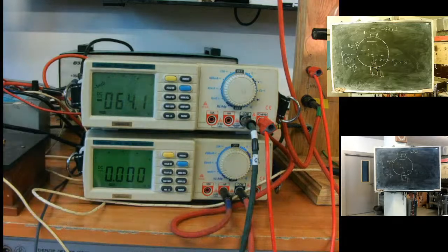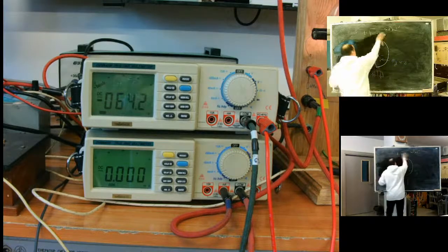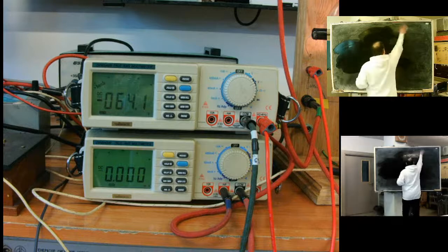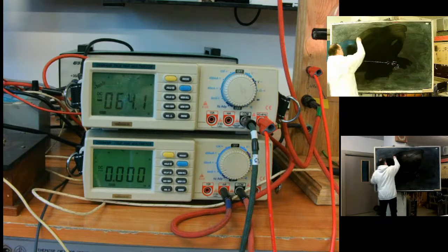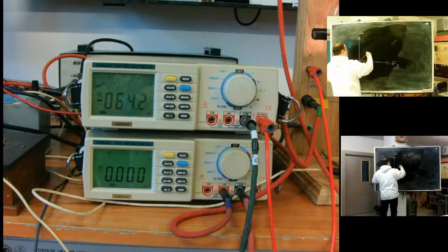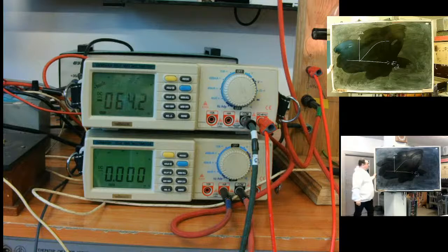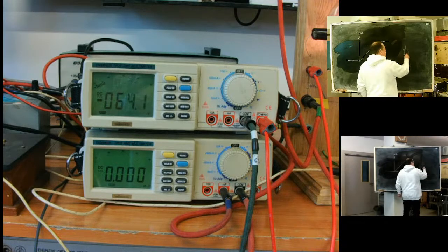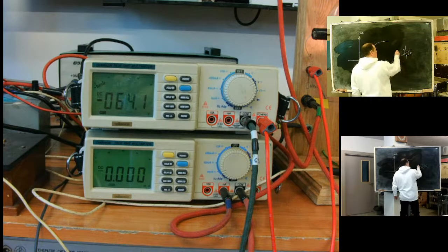I can draw a small curve. Of course, it's an approximation. Anode current. What we see? Nothing, growing, and then saturation. Something like this. So this valve can be seen as a resistance, Ri, the internal resistance. A resistance, but controlled by the grid.